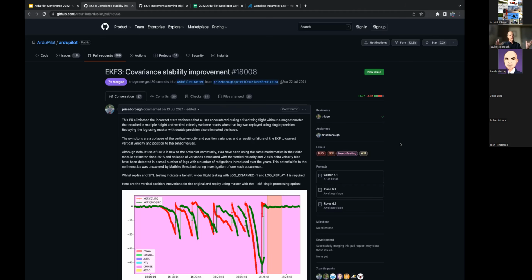but there are two different industry-accepted methods for how you go from a set of quaternions, which describe the orientation, because we use quaternions in the EKF to describe the rotation of the vehicle. You can then define the rotational direction cosine matrix, which rotates a vector from body frame to earth frame, and there are ways to express that as a function of the quaternions. There's one method, the one I'd use, which is pretty much the default you'll find in aircraft dynamics textbooks and flight dynamic simulations. And there was an alternative method which is used by the computer graphics industry.